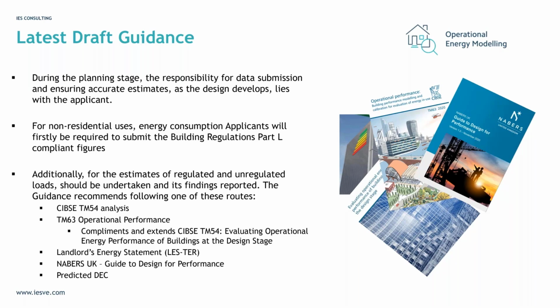We would also suggest that the use of seasonal efficiencies is likely to prove inadequate for this type of assessment, and a detailed HVAC network should be developed at the earliest design stage possible to ensure realistic part load efficiencies are accounted for effectively.